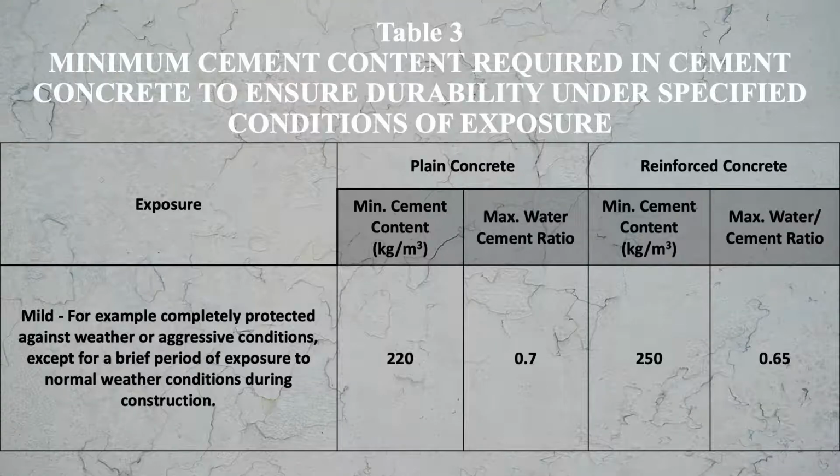So table 3 here gives the minimum cement content required in cement concrete to ensure durability under specific conditions of exposure. What are the different exposure conditions? Then for plain concrete and for reinforced concrete, that minimum cement content is given. So for the exposure condition of mild, for example, completely protected against weather or aggressive conditions, except for a brief period of exposure to normal weather conditions during construction.